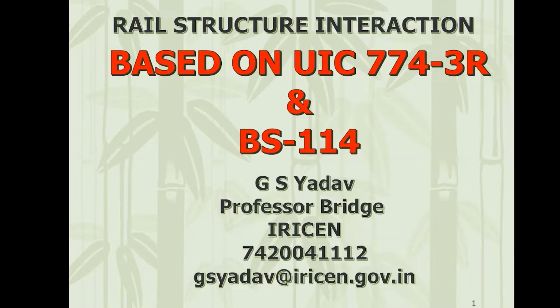So basically, this issue is not applicable in highway bridges, because in highway bridges, there is a bridge deck, and on top of the bridge deck there is no other structure. You have a simple girder and slab, and the road that you have built on top is part of the bridge deck, then you have the expansion joints. So there is no other structure on top of the bridge deck in highway bridges. So this issue is not applicable there.